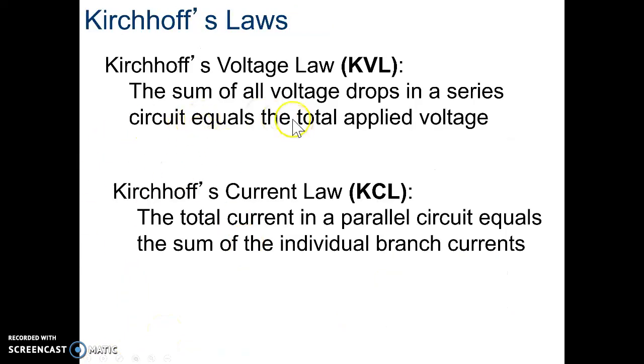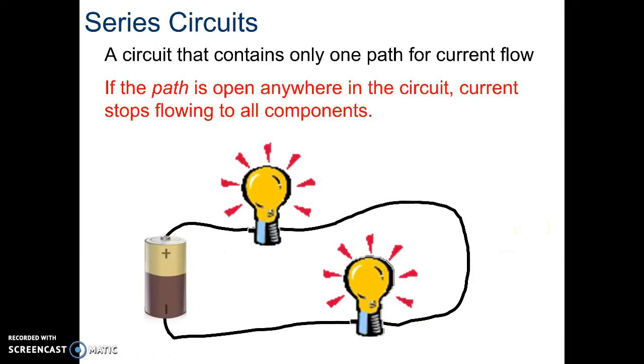Kirchhoff's law, Kirchhoff's voltage law, and Kirchhoff's current law. On the Project Lead the Way test at the end of the year, you're going to need to know both of these, and these are going to come in handy when you're doing the problems. The sum of all the voltage drops in a series circuit equals the total applied voltage, and the total current in a parallel circuit equals the sum of the individual branch currents.